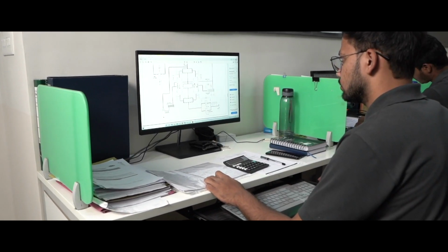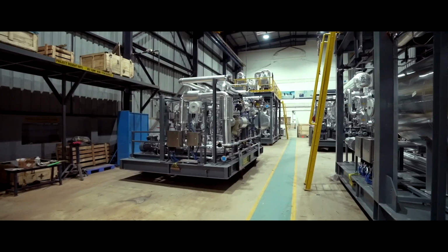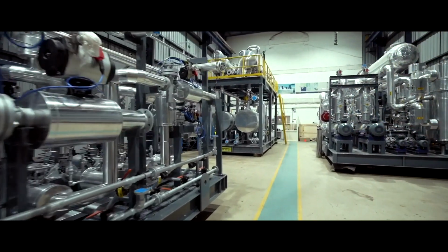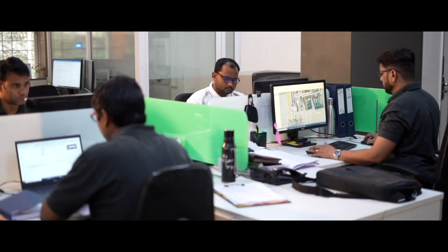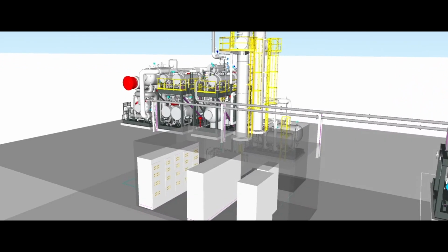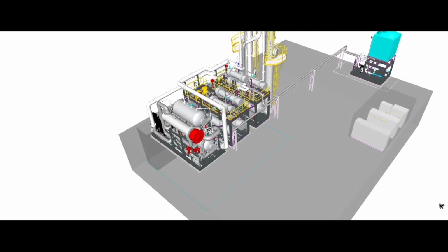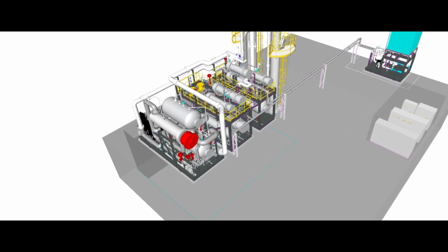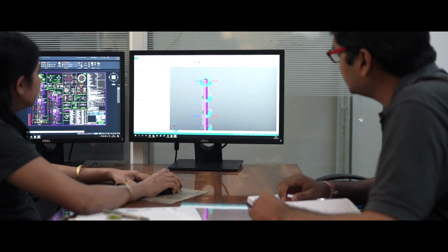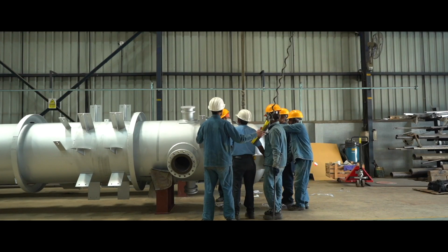The most critical part of the modularization process is to develop a P&ID, which helps to easily distribute the equipment and components into self-contained skids. The development of a detailed 3D model follows. This is a kerosene purification plant using the distillation process. Due to height restrictions applicable at the site in Kuwait, the distillation tower had to be divided into two separate towers which operate in series.